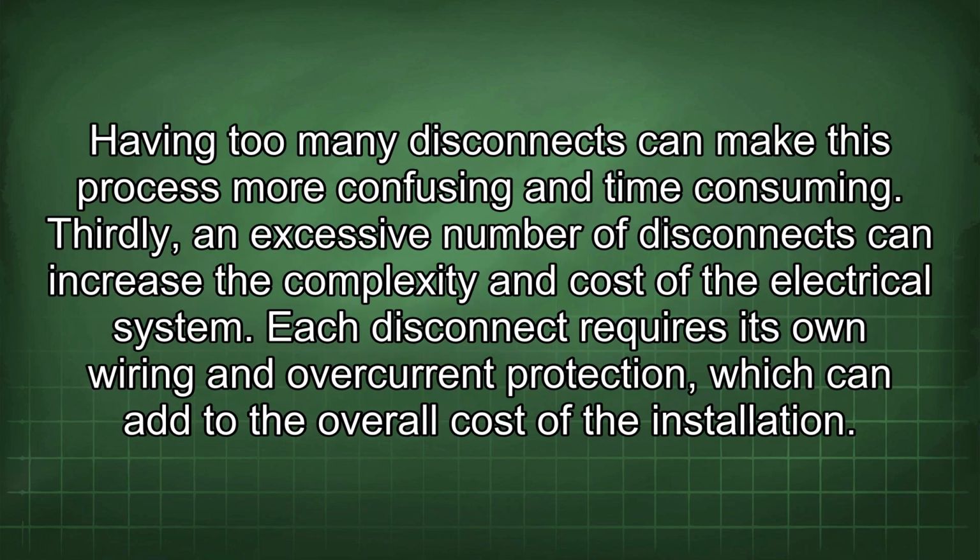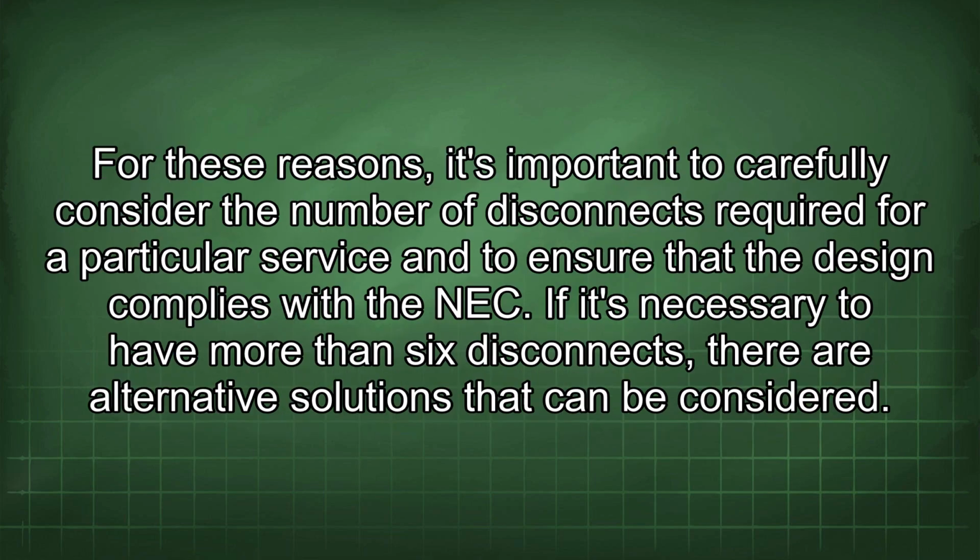Having too many disconnects can make this process more confusing and time-consuming. Thirdly, an excessive number of disconnects can increase the complexity and cost of the electrical system. Each disconnect requires its own wiring and overcurrent protection, which can add to the overall cost of the installation. For these reasons, it's important to carefully consider the number of disconnects required for a particular service and to ensure that the design complies with the NEC.